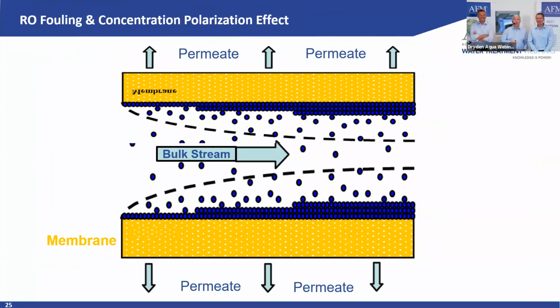Let's look here at what are these fouling. This is actually an important one, that's actually key. A little bit more into details now. Here we have the membranes, as you have seen before, the membrane module. They are in a sandwich position. In the middle is the spacer. The water flows from left to the right. The water is forced by the pressure through the membrane, so you generate permeate, and that's permeate on both sides, of course.